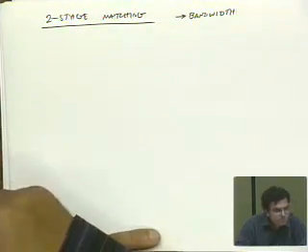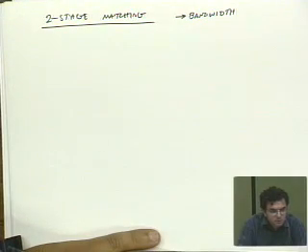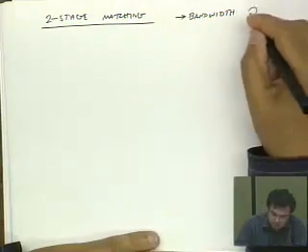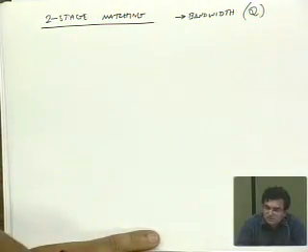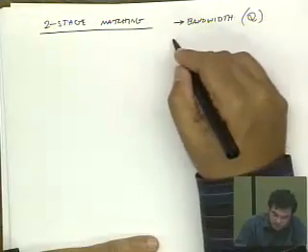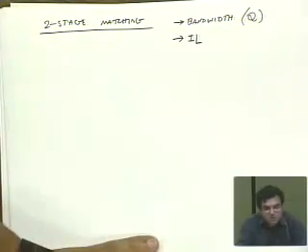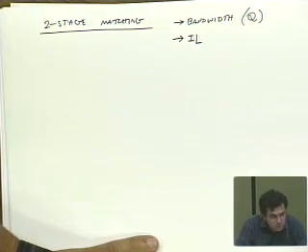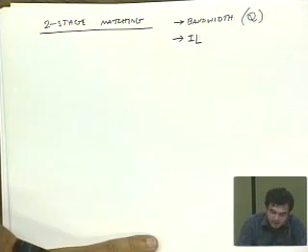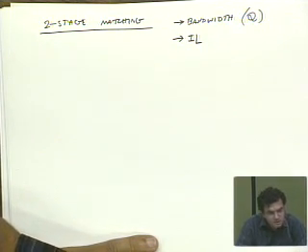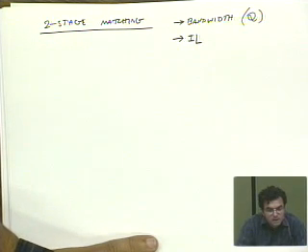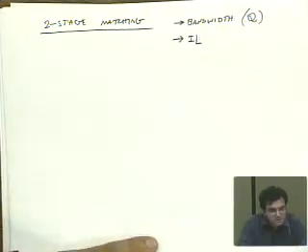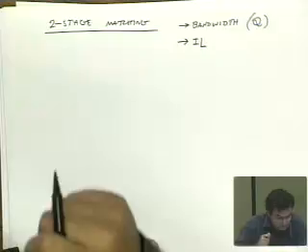What else? Another degree of freedom. Another degree of freedom for what? To design the Q, for example. Okay, but that's bandwidth, right? Yeah. Okay, anything else? Well, how about insertion loss? Is it possible that by using more stages we can get less insertion loss? In fact, it's true, you can. The reason is that insertion loss is really related to the network quality factor. And in certain circuits that have extremely high network quality factors, using multiple stages can actually relax the quality factor. We'll see how that works out in a moment.